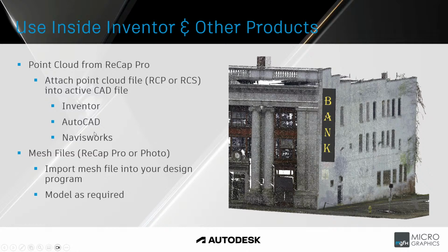Now I'm going to go specifically into Inventor. It's the product that I'm more comfortable with, and we'll have a look in there just to see how that comes through and what we can do with it. If we have the time, I can also open up AutoCAD and throw it into AutoCAD. The mesh files that come from Recap Pro, where we do the point cloud to mesh, or from Recap Photo, we can import that mesh file into your design program, like I said, of your choice. It's a generic STL file format or OBJ file format, and then you model as required from there.